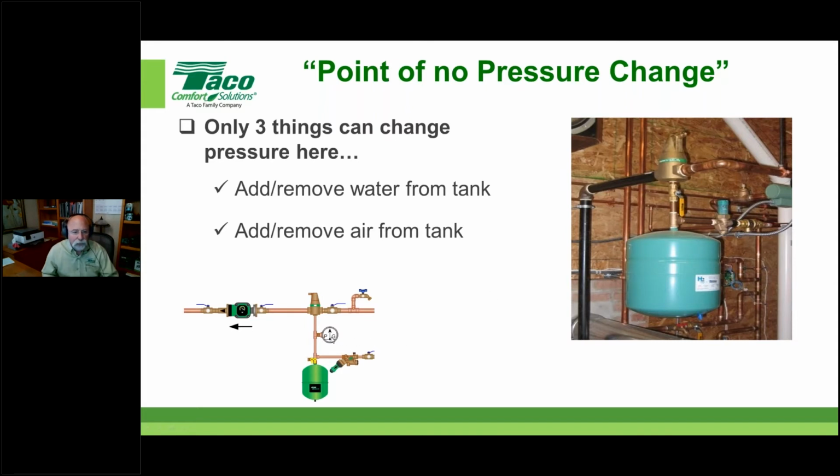Okay. Again, some of you have heard me get on my soapbox there. Realistically, this is the only place you ever want to see what the pressure of the system is. It doesn't matter what the pressure is of the boilers nowadays. These small, relatively speaking, low fluid quantity boilers, it doesn't really matter what the pressure is. We want to know what the temperature is, but we don't really need the traditional tridicator, thermo-altimeter type gauges there anymore. That was kind of old code stuff.